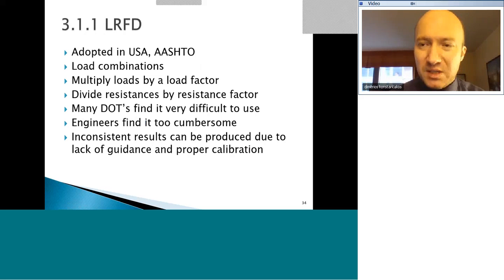Even DOTs themselves find it very difficult to use. Engineers also find it very complicated. We'll see that you can have quite some inconsistencies, and these inconsistencies are probably due to lack of guidance and proper calibration. And I'm not the only one saying not to use AASHTO LRFD combinations for excavations. There are also some other professionals, I don't want to quote their names right now. They're actually teaching a course on LRFD, and they say do not use it for design.